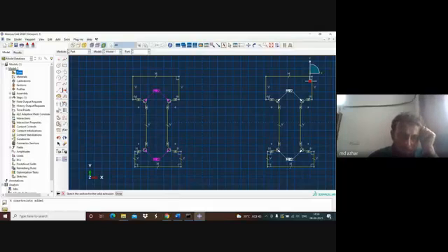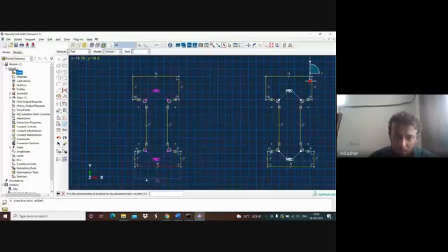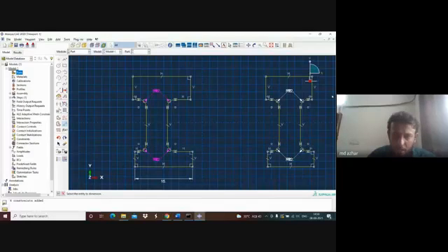Okay. Then you'll have the auto dimensioning part. So you can create the auto dimensioning from here. Then you can see the smart dimension, add dimensions here. Now let us suppose that you want to increase the length of it to 15. So the length of this is increased to 15.